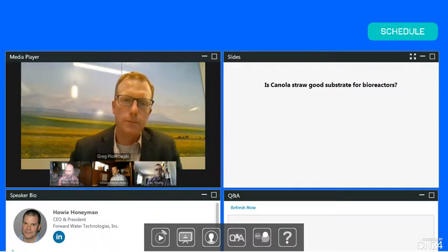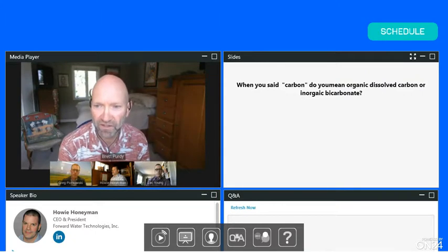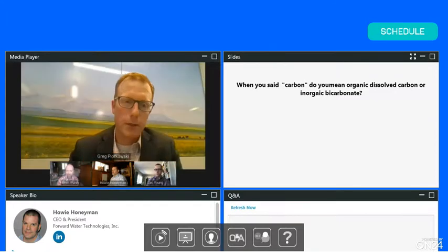Okay, thanks. So I'll pass one more question here and then move over to Zach. So when you say carbon, do you mean DOC or organic dissolved carbon, or does it include inorganic? Yeah, so apologies for missing that. It is the DOC. So denitrification is a heterotrophic process. So they are using organic carbon for their energy production, and then the nitrate, of course, is just accepting that electron. So the DOC is what I mean, and that's what's really driving the changes in removal performance that we're seeing.